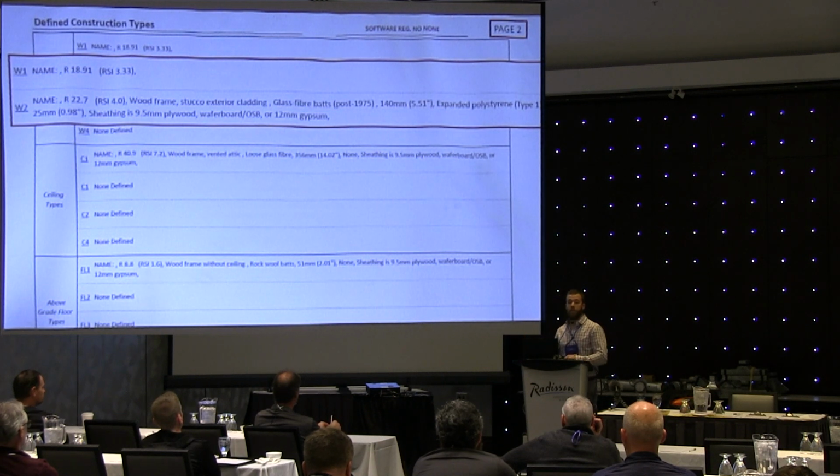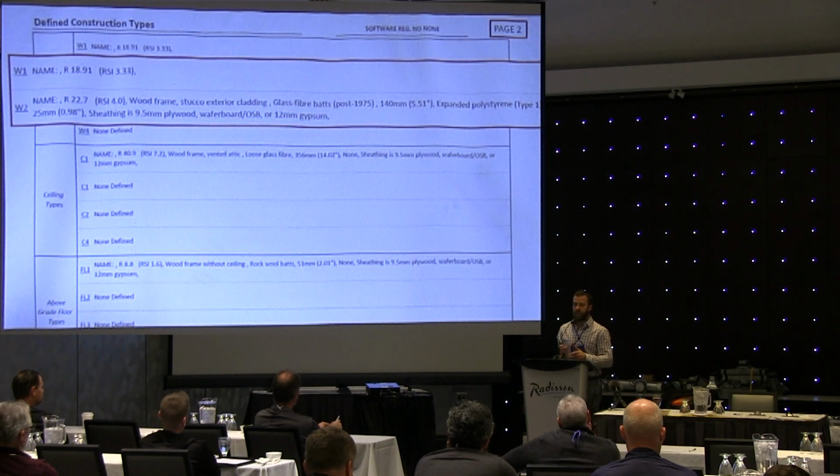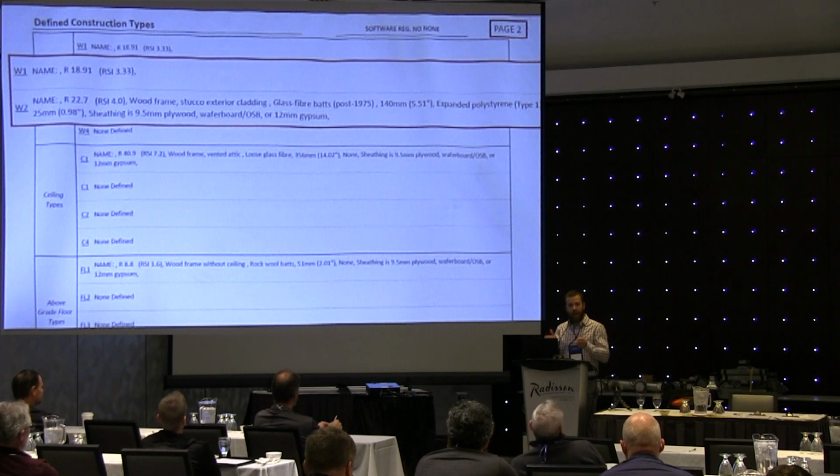Nominal, right? Which is the actual insulation value of the insulation only inside of the wall cavity. That's what nominal is. It's just talking about the insulation. But every element, every piece of that wall has some insulation value. So when we say effective thermal resistance, we're talking about every component mathematically added up together to give you the total R value of that assembly.